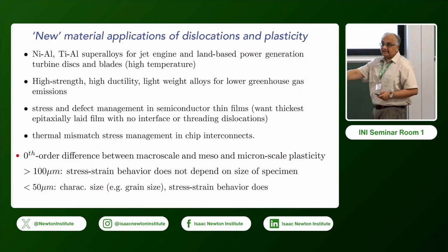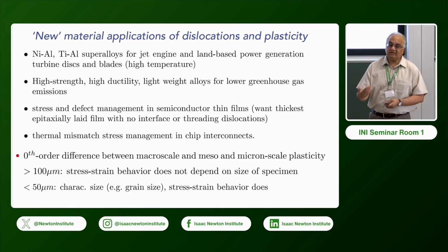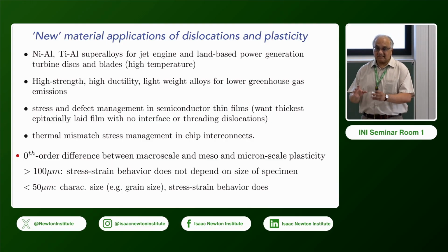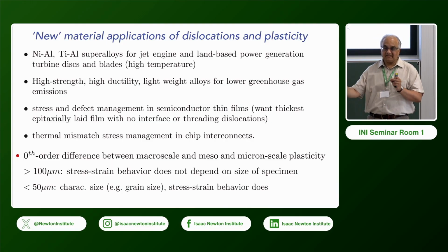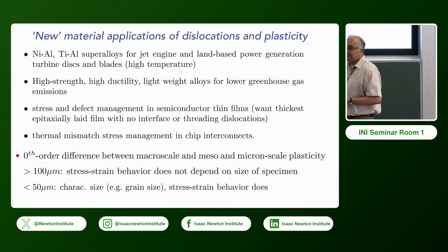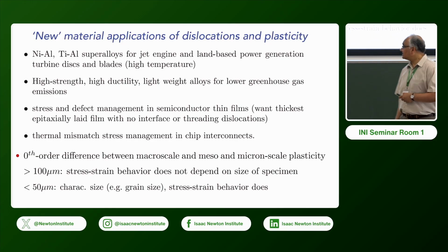Similarly, in interconnects, connecting chips, there is the thermal mismatch. So you have substrates, you have metals, and there are very high temperatures because of the resistance of these very thin wires. The metal wants to do something different from the substrate. You have huge thermal mismatch stresses. You don't want the interconnects to break. Again, it's a question of plasticity.